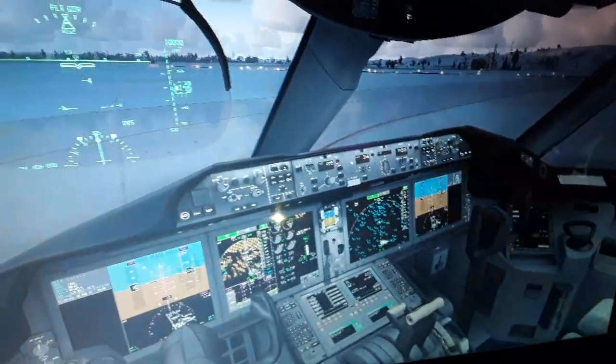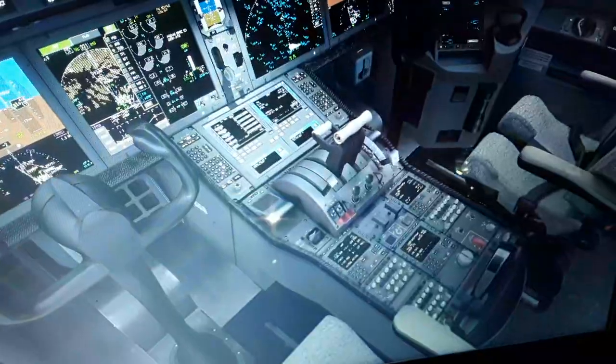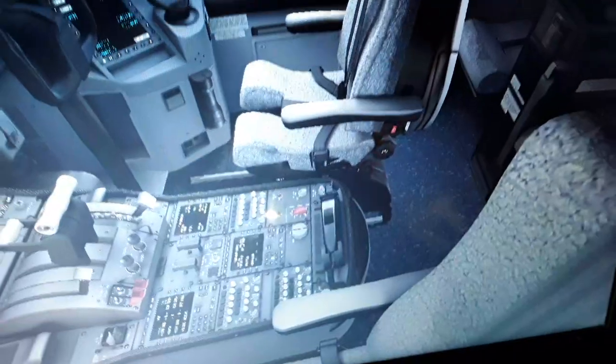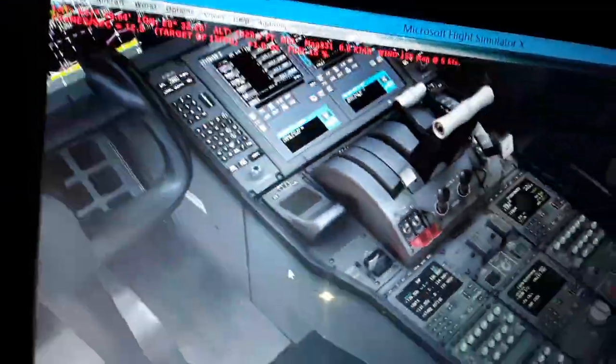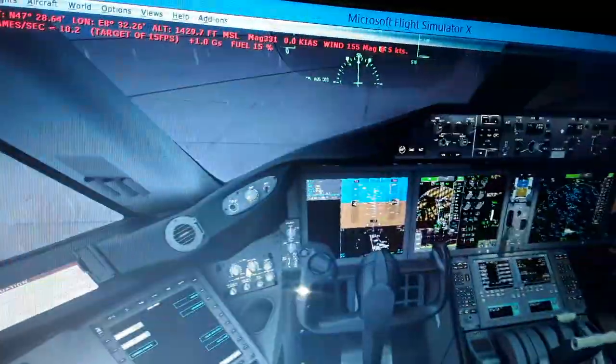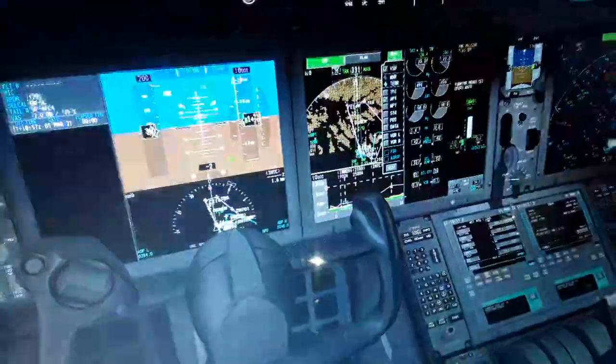If on the autopilot flight director system panel the auto trim function malfunctions, you open the guarded switch here and disconnect from normal to cutoff. Then you can use, I believe, the alternate pitch trim, and also you use all the time the manual pitch trim here. You always have manual pitch trim like this.